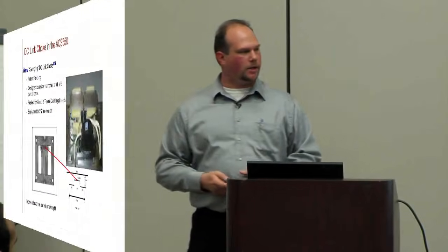Voltage drop. So you get more and more voltage drop, and now you might be hurting yourself because you can't get enough voltage to your motor. So now you're voltage starving your motor. There are other things that occur, so you have to be careful.